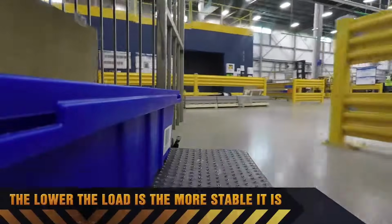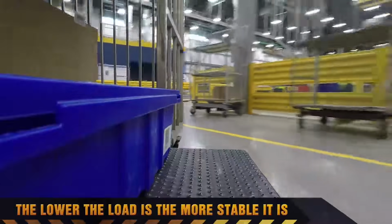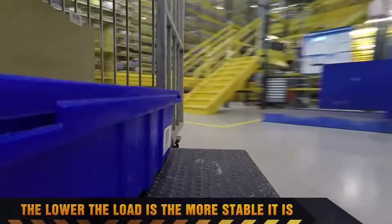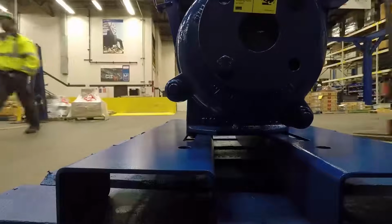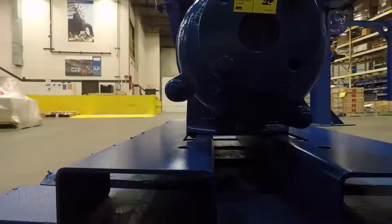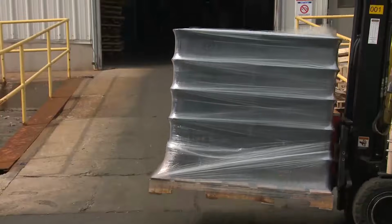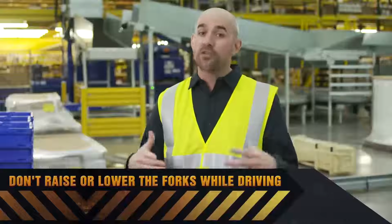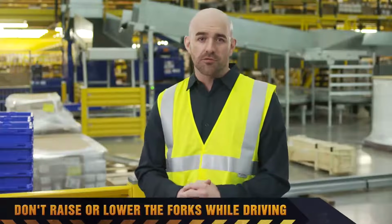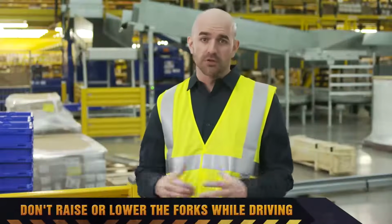Here are some general rules for safe travel with the load. Remember, the lower the load is, the more stable it is. Always travel with the forks and load as high as necessary to clear the travel surface, but no higher. And understand you may have to raise them slightly to travel over bumps or seams from time to time. But with all that said, don't raise or lower the forks while driving. Raising or lowering the forks while driving causes the forklift and the load's combined center of gravity to shift unpredictably, increasing your chances of tipping over.